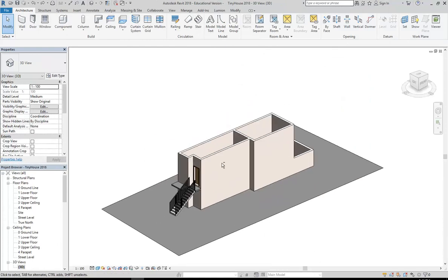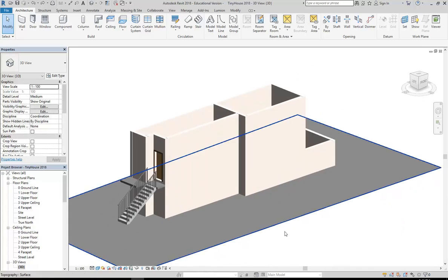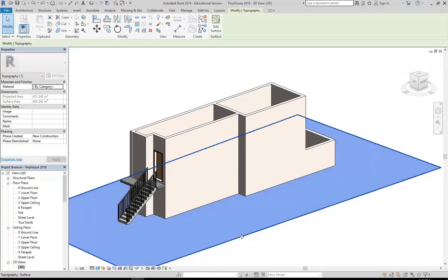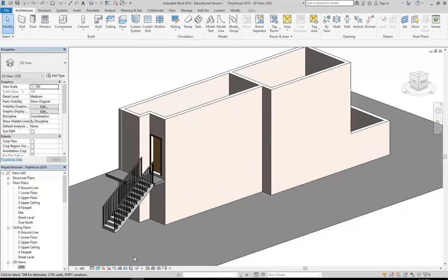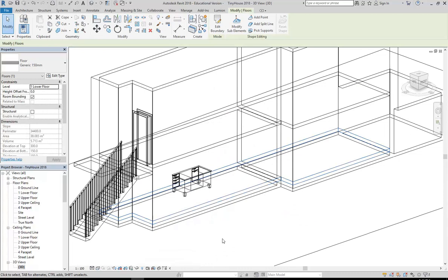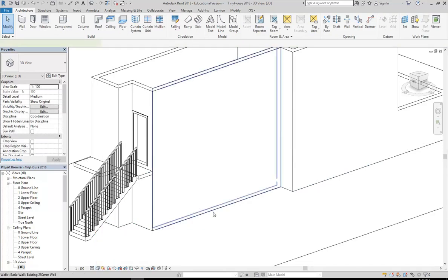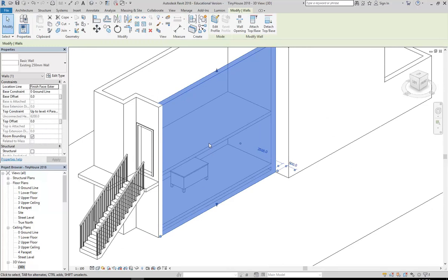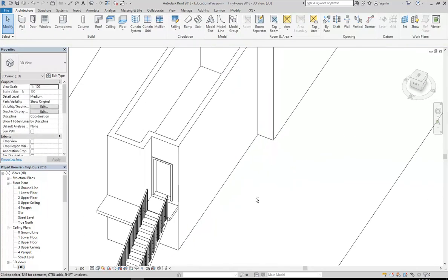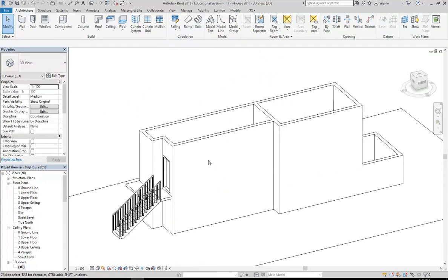So you generally want to have obviously the outer walls, and then it's good if you have a site like we've made already, the topo surface. But then probably even more important than that, the floors. So I've got there a floor on my bottom level. Just drawn the wireframe so you can see that, but I'll go back to hidden line now, and you can see that I've got a floor on the upper level as well. And so now to enclose these spaces, I need to put a roof on top. I'll add a ceiling as well, but I'll start with the roof.